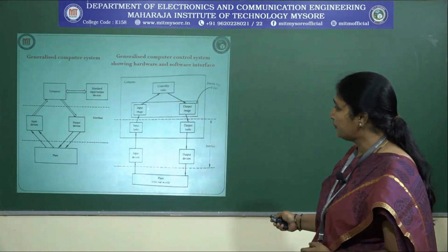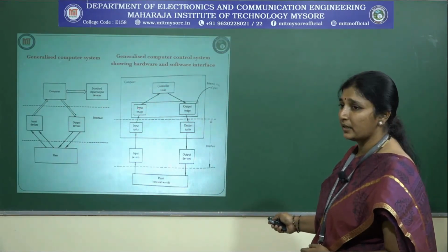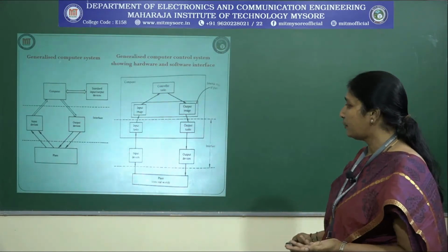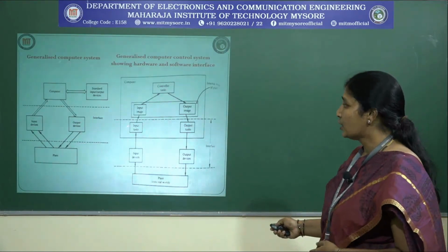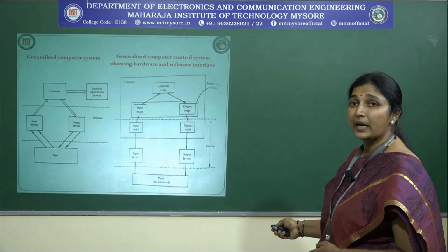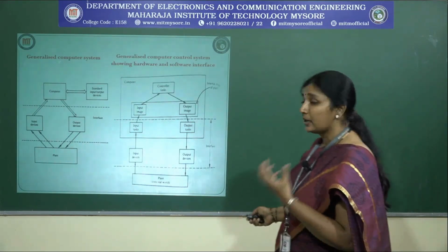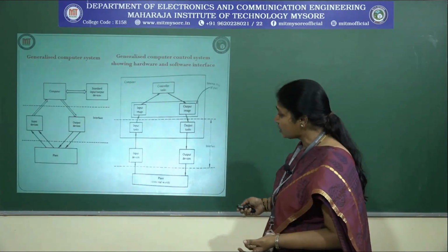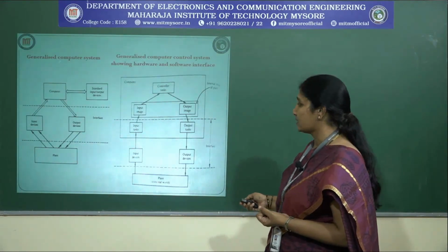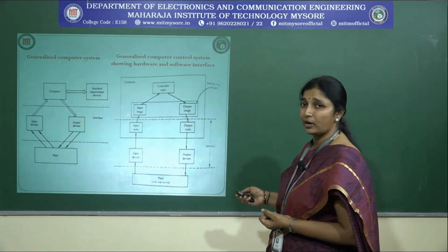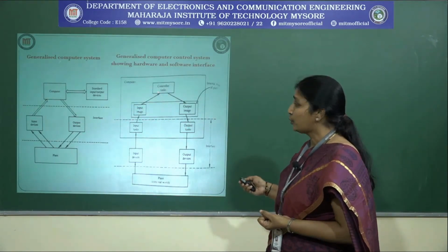The input image that is generated here is the state of the plant at that instant, okay. So the input task replicates the input program. What is the input task? It gathers all the information from the input devices and sets up a screenshot at the input of the controller.